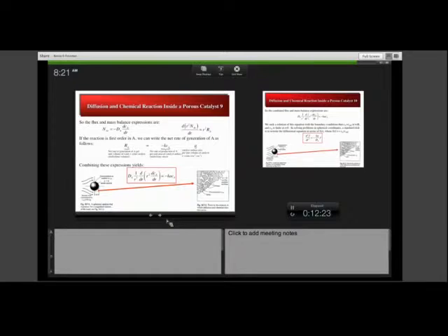But once we apply this averaging, then those diffusion coefficients also get averaged over the structure of that catalyst particle and are no longer material properties in the way that we normally think of diffusion coefficients. So one of the pluses and minuses of this approach: one, it greatly simplifies the mathematics of analysis of the problem. Now, that's a plus. The minus is that you have to inject additional knowledge, or you lose knowledge about the details of the structure of the catalyst particle, the tortuosity and exact pore structure.